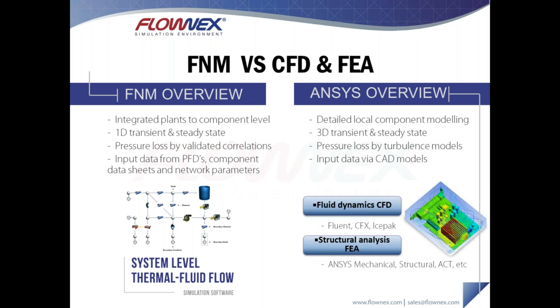And the software itself, or this particular flavor of software, is designed to provide a very intuitive and very easy to use user interface where users can insert components to model the parts of the plant as they see it. So models would exist for pipes, for pumps, for compressors, for valves, for tanks, for containers, turbines. All of these components are represented inside of the components library, and then users can just choose components that are relevant to their particular plant, insert them, creating a small network very similar to a process flow diagram, and then the network itself can be solved and produce results for both the flow and for the temperature and heat transfer